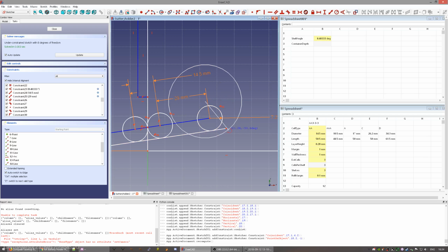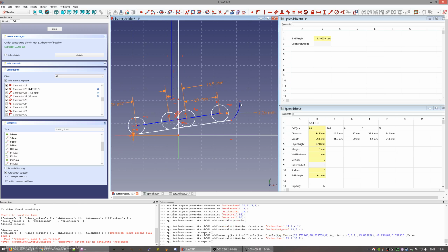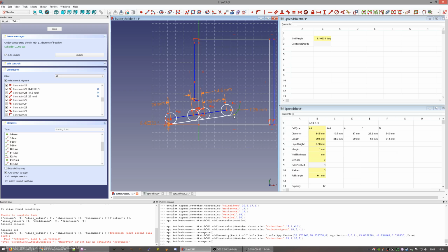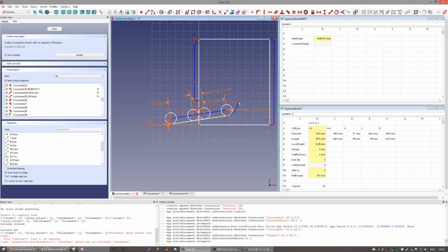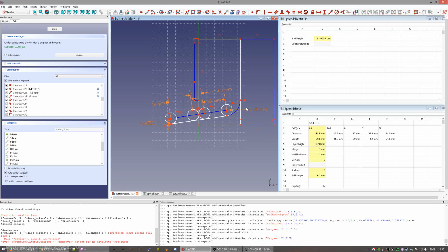And obviously the shelf will end at some point and the circular arc will go up, and I don't want these to have a corner, so I use T, and FreeCAD switches it to an endpoint to endpoint tangency and removes the coincident constraint. That's just FreeCAD actually being helpful instead of failing something. And we touch this wall as well.